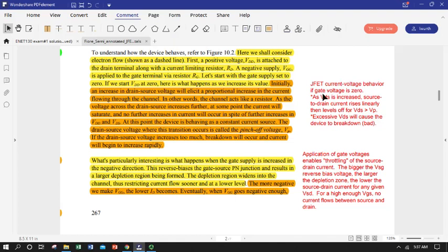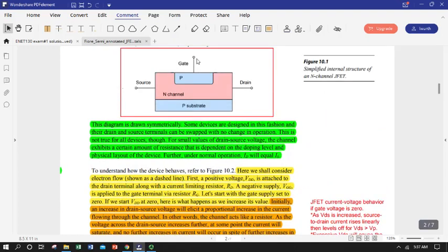Let's start out where the gate is open. We don't apply any signal. If we just want to flow some current between source and drain, we've just got a big piece of a single monolithic semiconductor material, which is, as long as we get across whatever junction potential at the metallized contacts on the edges, no problem. I can flow current through this. This is going to act like a reasonable conductor with just a little bit of forward voltage.